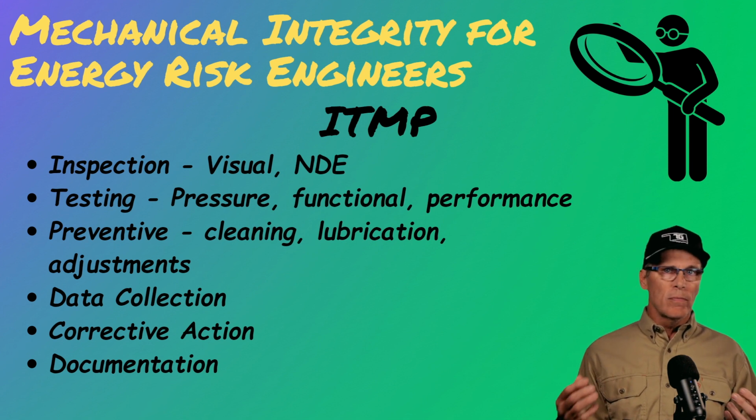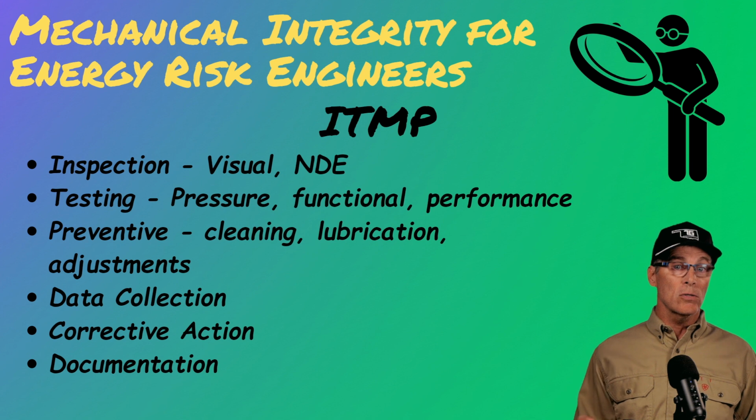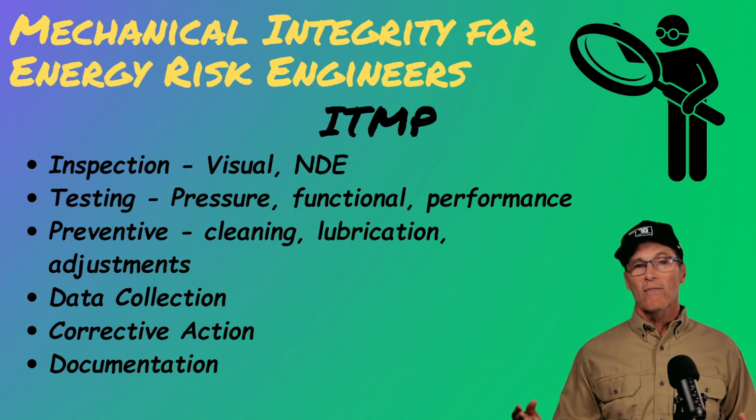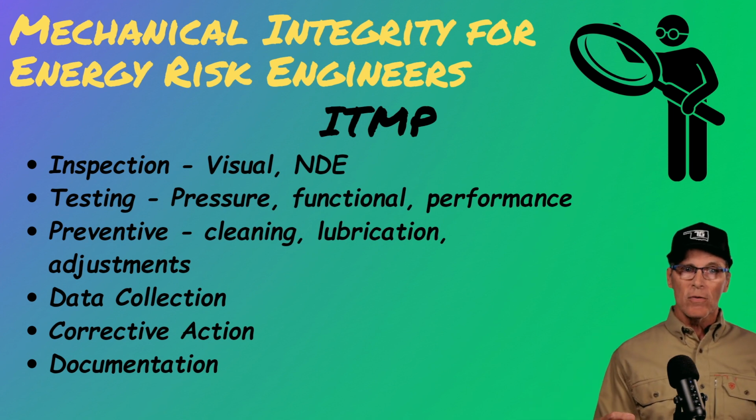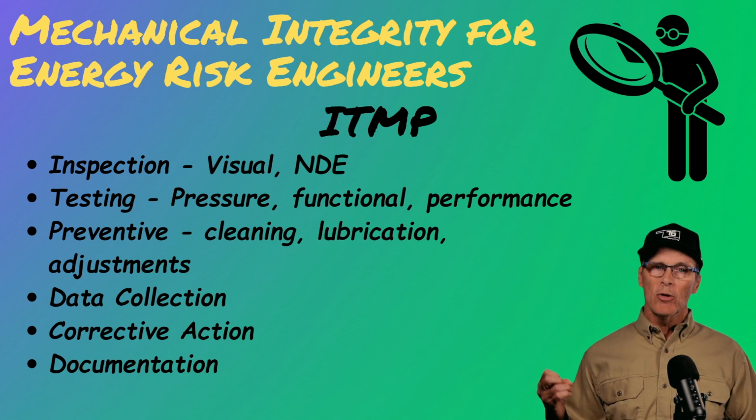Testing, that's when you put equipment or systems under pressure tests, functional tests, performance tests. You're looking to see what kind of flow rates, what kind of output you can get from the system. Preventative part of the maintenance, you're cleaning things, lubricating them, you're making adjustments.